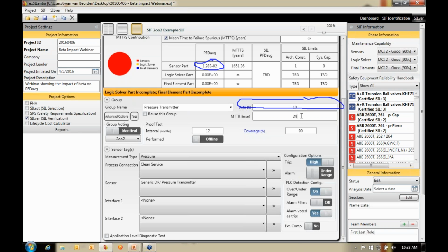It's minimal. There's only a small drop, but it drops because the system behaves more like a non-redundant system. And non-redundant, 1 out of 1, is safer than 2 out of 2, probability of failure on demand-wise. So we see, if we go from 0%, with 2% it drops, with 5% it drops more, and then with 10% we go to the 1.28. It doesn't have as big of an impact as we saw in the 1 out of 2. For 1 out of 2, we went an order of magnitude between no common cause and common cause with 10%.